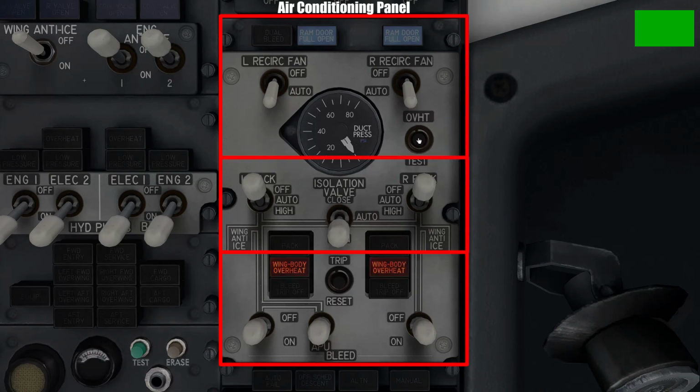Come underneath, we have 3 important switches pertaining to the PAC systems in the aircraft. These 2 switches allow the pilots to switch between turning the PACs off, to their automatic mode, or to high mode, wherein the PACs will work faster to cool bleed air that is coming from the engines. It's important to note, however, that the PAC systems are normally left in the auto position so as to let the automatic air conditioning systems in the aircraft decide the optimal usage for the PAC systems.